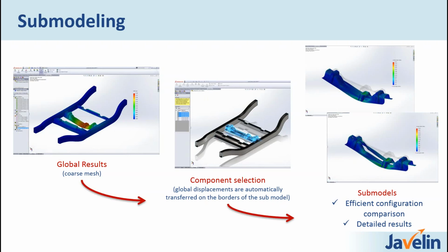So what we can do now in that one component, we could try finer and finer meshes to run a convergence study on the part. We could even try small design changes, like going in, making weight-reducing cutouts, changing geometry slightly. The only thing to keep in mind there is, for example, you look at this picture on the very bottom right, we've got a weight-reducing cutout down there.